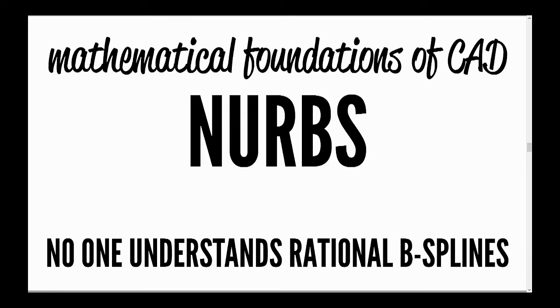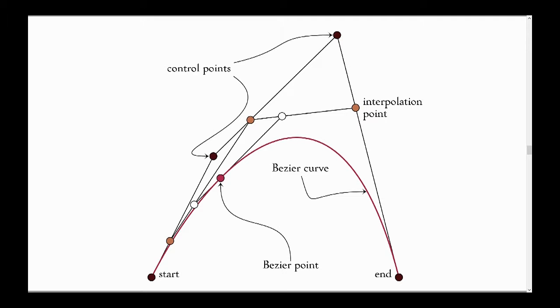To give you a quick intro into the mathematical definition of NURB surfaces, this is a basic NURB spline. You see that those four brown points are the input, the control points. The orange points are, let's say, at about a third of the distance between the points. The pink point on the Bezier spline is also at about a third of its length.